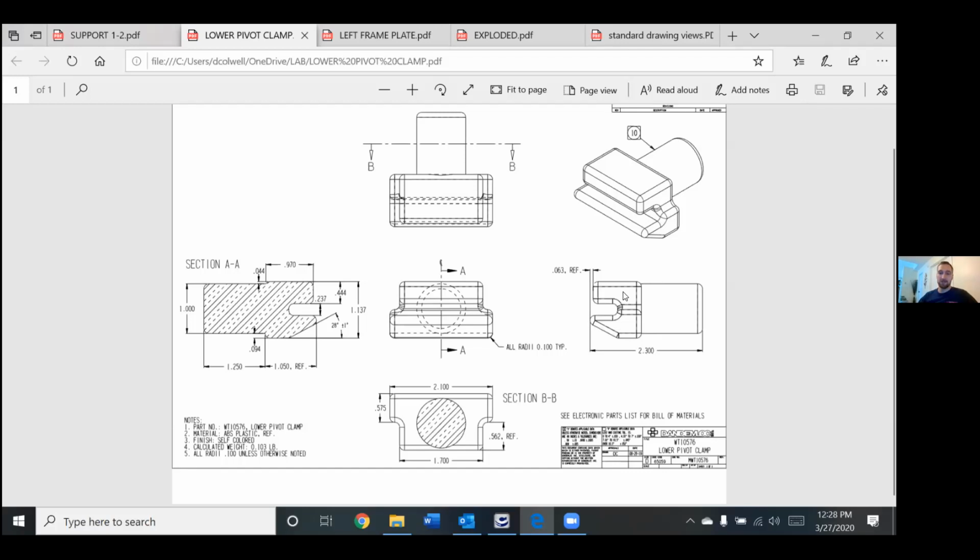But it seems to me that it shows that better. So I would recommend, and again, that's going to be where you work and what their policies are, tangent lines on or off is not really a hard rule. That's why it's an option in your CAD software. Do what best conveys the information. And if you're looking at that part and you don't see those tangent lines, it might be kind of confusing what you're looking at. To me, I'm used to seeing them, so I leave them turned on. That's how I've always seen them drawn. But that's what's going on here.